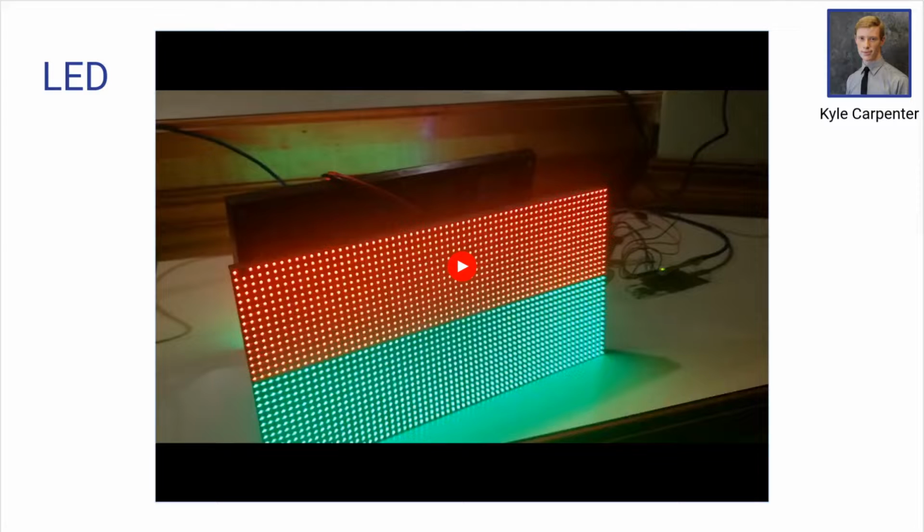And after every latch, you have 16 lines. You have 16 different lines that need to be displayed at once. So it's a 1 in 16 scan rate. By having this system, we can basically push out the 384 bits 16 times, and it'll flash between those 16 different configurations, which then illuminates the entire screen. And this allows us to control every aspect of the display.